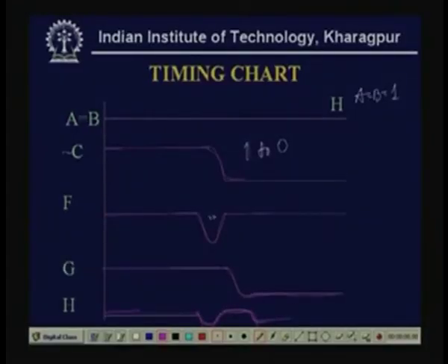See here F, we are calling this a static hazard. Now with this hazard also for this particular circuit, when we have included another inverter and the AND gate, then we are getting some more added glitch. See this one for the H, this is some more one for this. This is called the dynamic hazards.